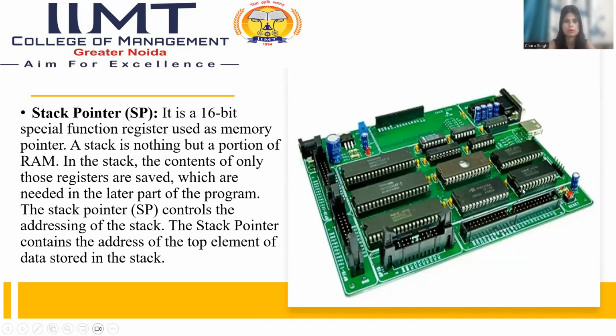Next, let's talk about the stack pointer. Basically, the stack pointer is a 16-bit special function register used as a memory pointer. A stack is nothing but a portion of RAM. In the stack, the contents of only those registers are saved which are needed in the later part of a program. The stack pointer controls the addressing of the stack. The stack pointer contains the address of the top element of data stored in the stack.